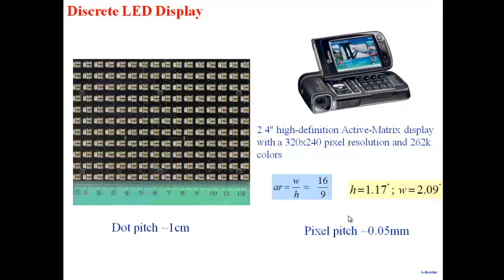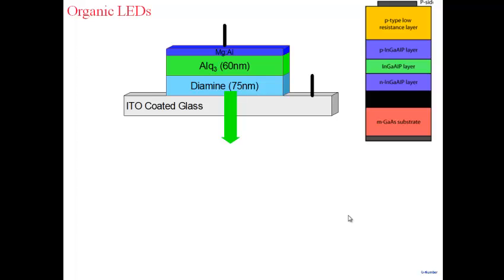Not only that, if I could integrate my LEDs on plastic, I could make an IC with LEDs as components on plastic. Then I could have flexible, very lightweight displays. You can see all the advantages that are there. But I can't do that using inorganic semiconductors. Why? Two reasons. Because they're crystalline. They work only when the material is crystalline. And second, they require high temperature processing. Both these reasons prevent me from doing things on plastic or paper and things like that. I can't do monolithic integration. Okay, so that brings us to organic now.